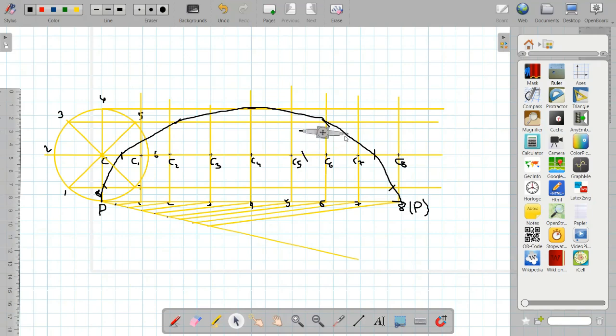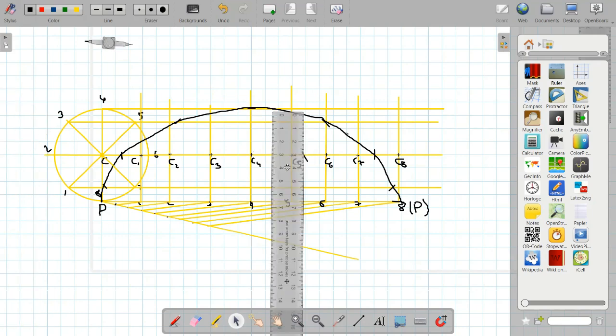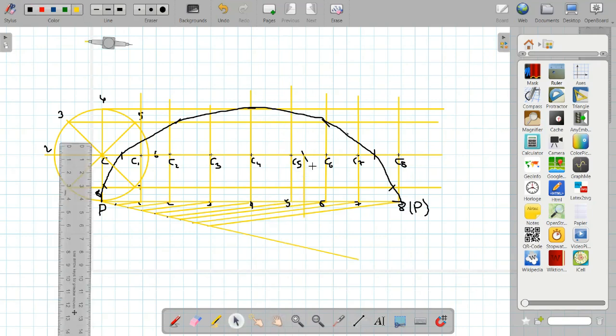Now, wherever it touches the center line or wherever it cuts at the center line, you have to draw one vertical line extending from this point to the bottom. Again, these will all be very light lines because they are construction lines. Wherever this vertical line cuts the horizontal line or the baseline, join this point with the point on which we want to make the normal and tangent.